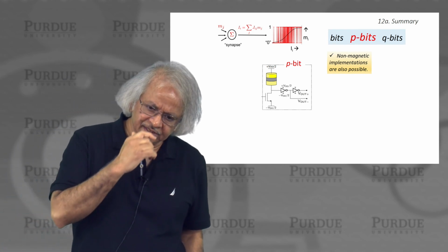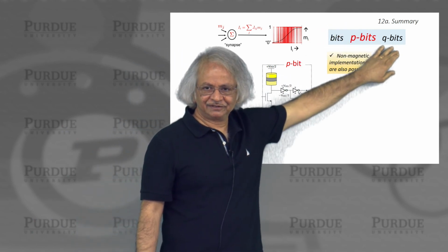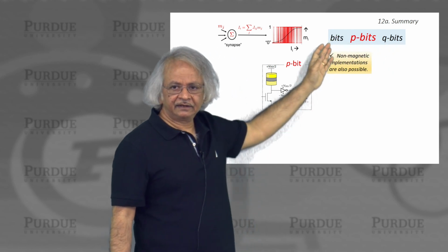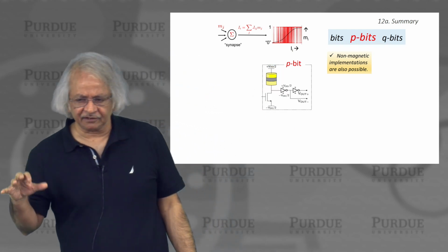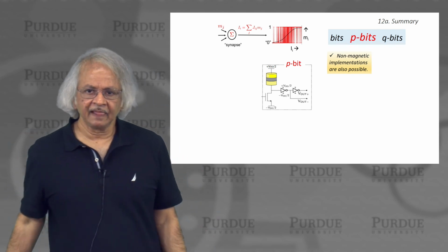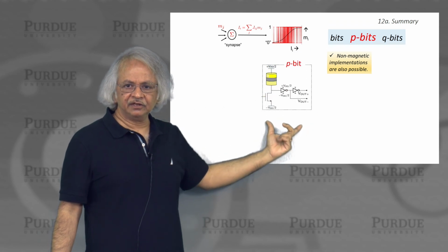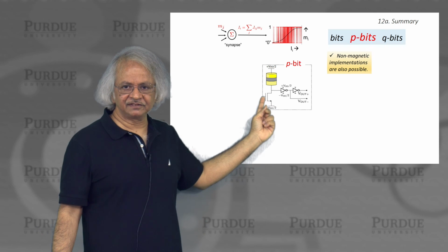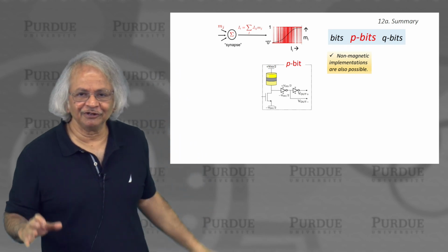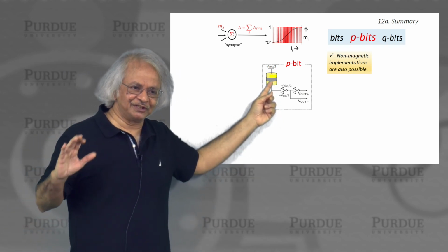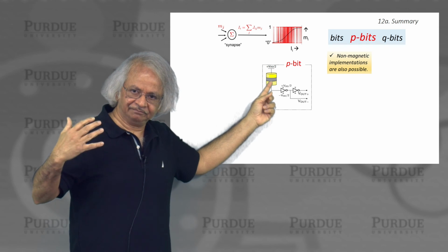What I want to tell you about is this concept of p bits, that's somewhere in between bits and qubits that you hear a lot about. And as I said, these p bits are a little like this binary stochastic neuron that forms kind of a subset of that field of neuromorphic computing. And a very natural way to implement the binary stochastic neuron is by using this embedded MRAM technology, where you have a transistor with an MTJ at its drain. But the only difference being, in that technology, you are usually trying to build good MTJs, which store 0 and 1, whereas what we want here is the bad ones, which fluctuate between them.